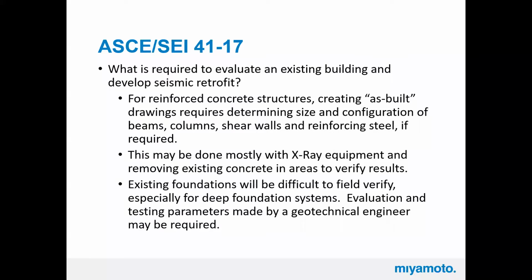If we don't have drawings available, then we have to create as-builts from trips to the building, documenting everything we can, or even engaging a testing lab to create as-builts through non-destructive or even destructive testing as needed. Usually that costs us a lot of time and a lot of money. Usually I find if we say we need to do that and here's how much it's going to cost, suddenly the drawings appear. So don't be afraid to try to find that information, because it's incredibly valuable.